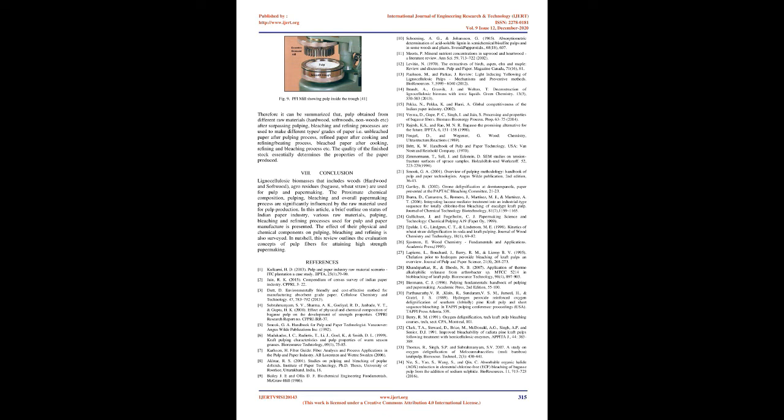Modern bleaching is achieved through a continuous sequence of process stages utilizing different chemicals and conditions in each stage. The commonly applied chemical treatments are chlorination, C, alkaline extraction, E, chlorine dioxide, D, oxygen, O, hypochlorite, H, peroxide, P, and ozone, Z. Bleaching of chemical pulps is achieved either with an oxidizing agent or a reducing agent. In bleaching, the main reaction mechanism is oxidation. The bleaching agents C, P, O, and Z are important and commonly used oxidants which cause depolymerization and create new hydrophilic groups.